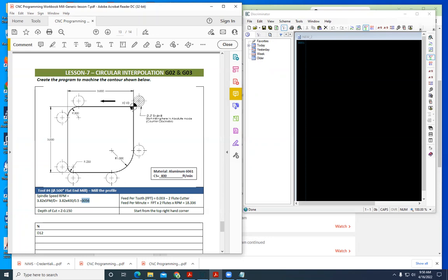We're going to calculate the distance from 0 to the center of the tool, and we'll write the program from the center point of the tool to the center point, and then we'll go counterclockwise, which would be G3, linear G1, counterclockwise G3, linear G1, counterclockwise G3, linear G1. And we can program these with R or I and J. R is much faster as we go through and we work this.